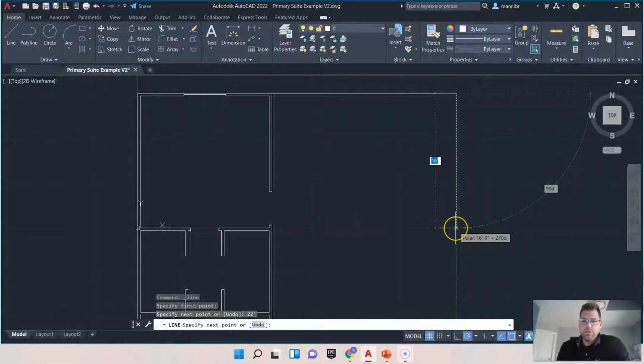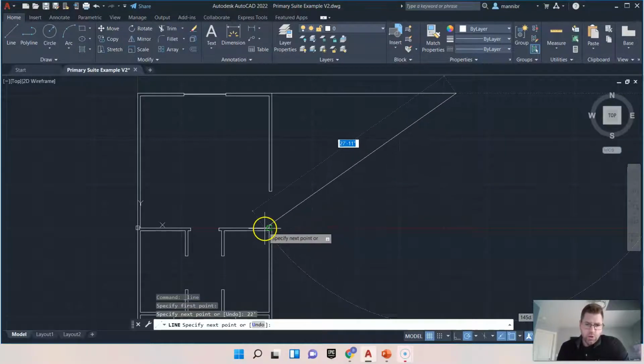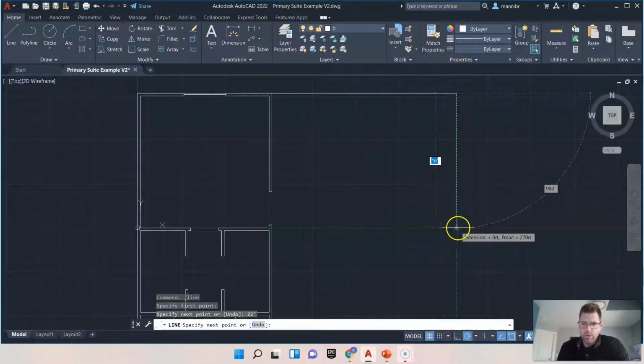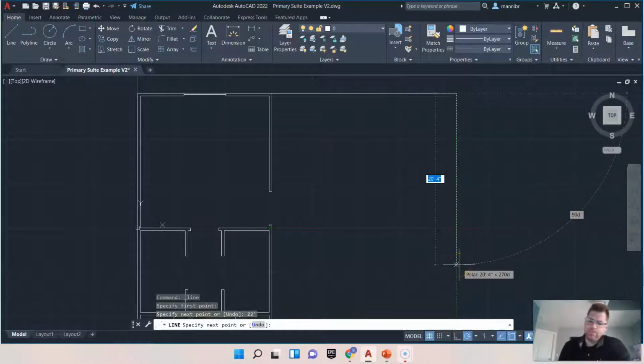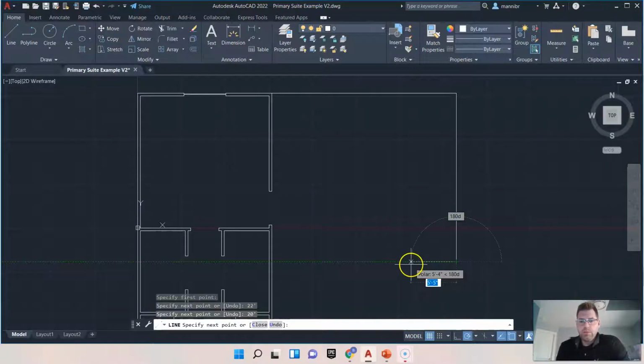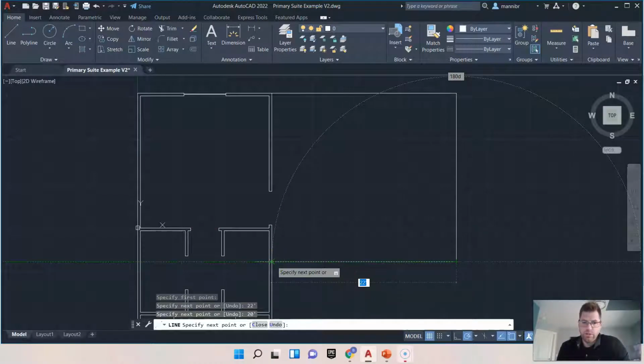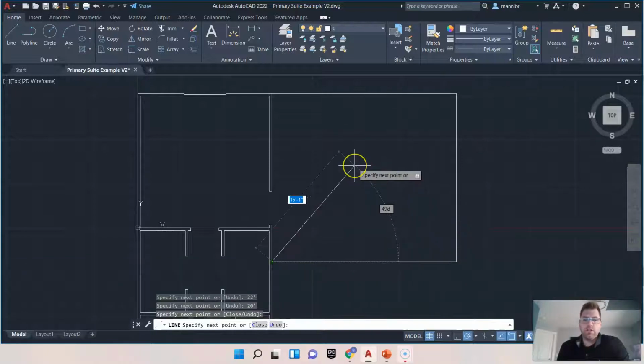And then I'm not going to be hung up on a size so much. I'm going to go over here and pull my polar snap out. And that's going to be 16 feet. Probably a little small for what I want. So I'm going to drift down and I'm going to type in 20. I want it to be a little bit rectangular, more than just straight boxy, 20 feet, and hit enter. And so this is what I mean by being able to set lines to length. Pretty straightforward. I'm just going to run this over to this edge of this wall and hit snap. Again, it's 22 feet. I do not have to type that in. It's going to be good.